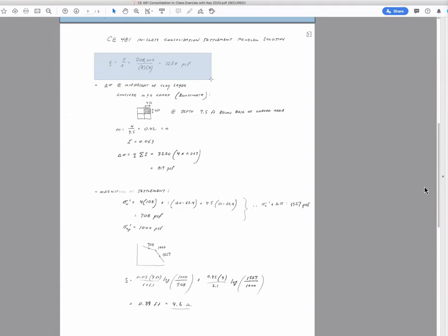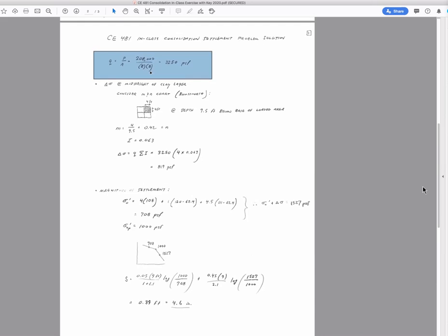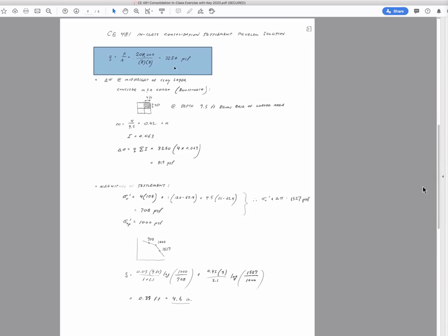And in order to get to that, we need a load at the surface. It is, after all, a foundation being placed on the surface in this simple example. And that's load over area, 208 kips over an 8x8 foundation. And that's 3250 psf. That is at the surface. So we use this value in the M&N chart as our loaded area at the surface.